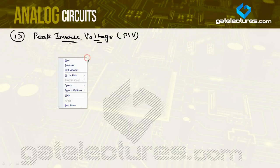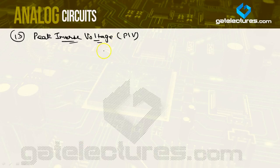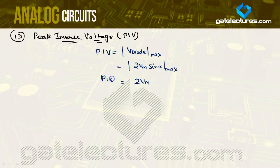So peak inverse voltage is the maximum inverse voltage across a diode. So we know that PIV is V diode maximum. This was 2 Vm sine alpha, maximum value. This will be equal to 2 Vm. So PIV is larger than in the half wave rectifier. This is important.